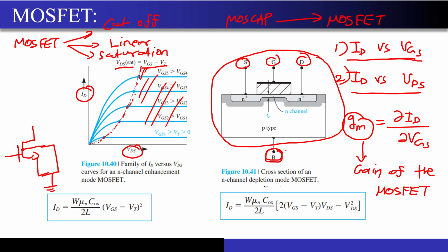But what if you have a circuit like this? For example, let's say this is the MOSFET. Let's say you put one MOSFET on top of the other MOSFET, right? Then what is going to happen? This is the body voltage, and this is the body terminal, and this is the source terminal over here, and this is the drain terminal, and this is the gate terminal, right? Generally if you ask a circuit designer, we say that we short the body with the source, right? But there are a few circuits where you apply a different voltage to the body compared to the source over here.